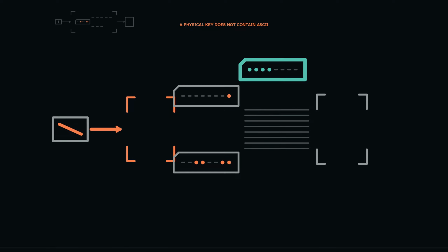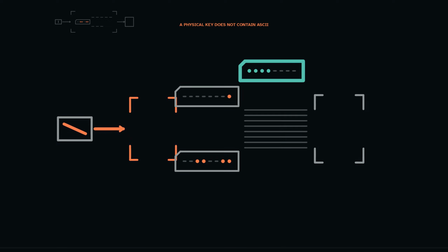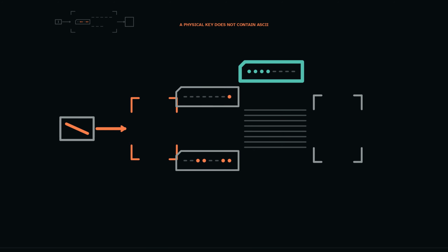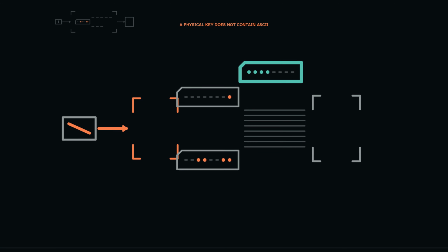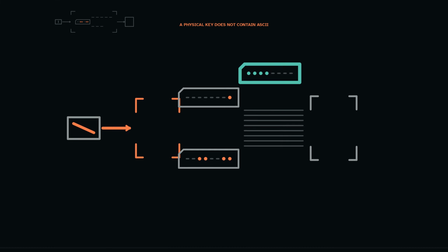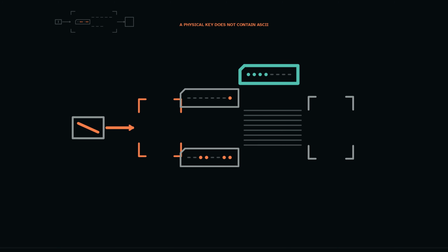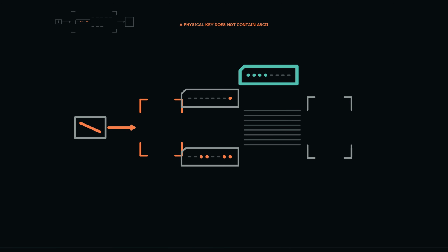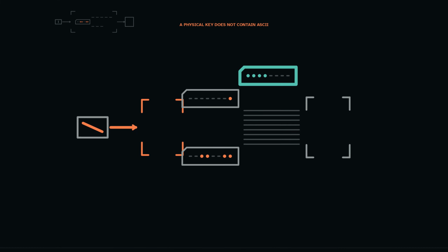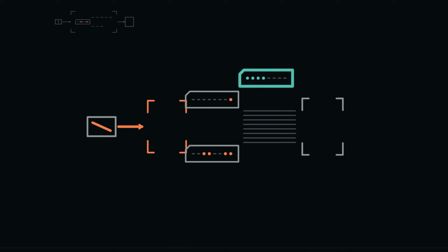SE8 has 256 possible byte addresses. Ordinary memory occupies hexadecimal 00 through EF. The upper addresses are reserved for devices. Hexadecimal F0 is keyboard status, F1 is keyboard data, F2 is display status, and F3 is display data. The address decoder still activates exactly one destination for every valid address. A device register is therefore reached through the same address selection structure as a memory byte, even though its read or write may cause a device-specific event.